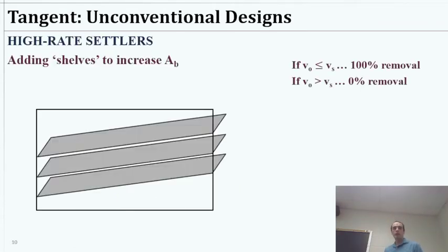All right, so there are a couple of interesting things we can do with sedimentation. One would be to increase the rate at which we can sediment things by simply making it shallower artificially. So this would be called a high rate settler. It requires just a little bit more infrastructure than a swimming pool. So you could just about use a swimming pool, flowing water through.